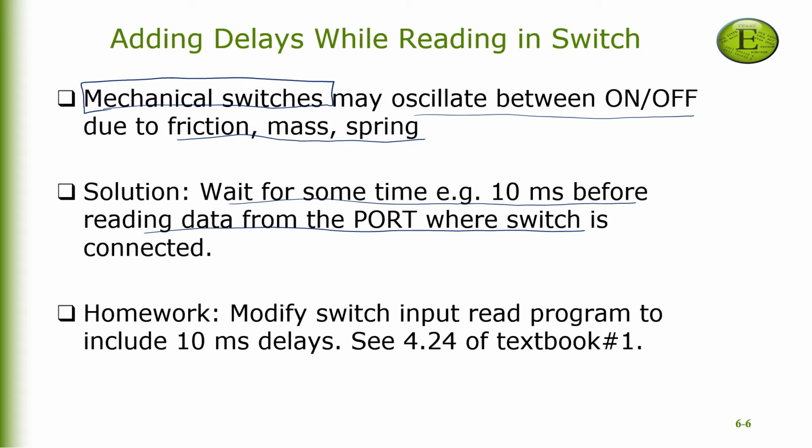But in the meantime, please look at figure 4.24 of textbook number 1, in which there's a flow chart that implements a pseudocode to read the logic level at the switch. It does that by introducing 10 millisecond delays. It's not a complicated program, very simple, and hopefully you can follow that easily.